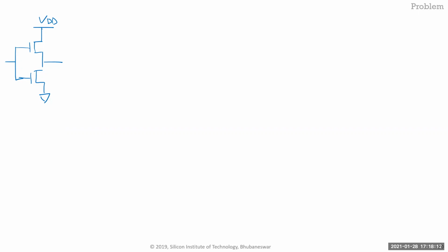R naught is inherent inside the transistor. That's what you get because of the transistor function, because of that lambda, the early voltage. The resistor we put between the input and output, we physically put there to bias it so that it stays in the middle. Okay. So yes, we have that resistor, but I'm going to ignore it in the small signal model because I'm going to say it's very big. But let's keep it for now.